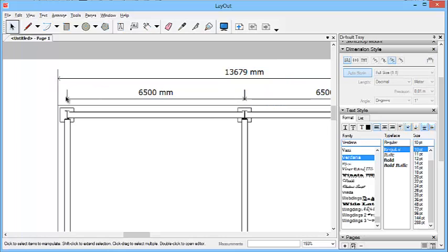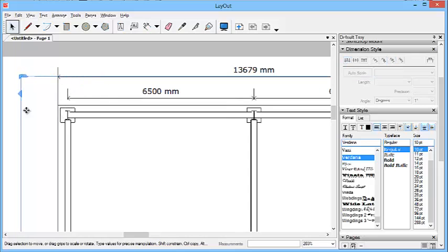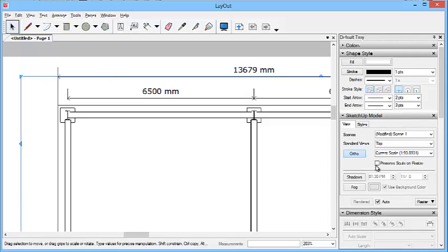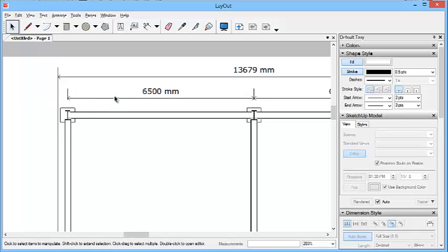The other thing I'd like to do is just extend this line down a bit further to see where it's actually taking the dimension from. So again, you have to be careful now because my viewport is kind of out there. If I do go into SketchUp model and make sure that's ticked, then I should be able to just drag this viewport window down a bit, so I'm not double clicking through it to activate it.